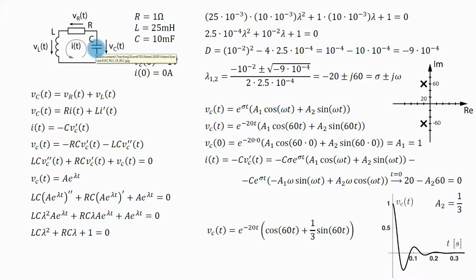The capacitor will start to discharge, except now with opposite sign of the current. Some energy is being transferred into the magnetic field of the inductor, which will keep the current flowing, and then it will charge this capacitor to opposite voltage. But in every cycle of this energy exchange, some energy is dissipated on this resistor, and that is why we have this exponential damping here, and that is why the amplitude of these oscillations is decreasing and the voltage on the capacitor is asymptotically approaching 0.